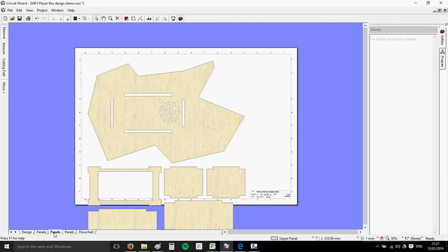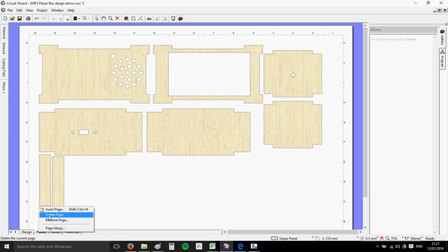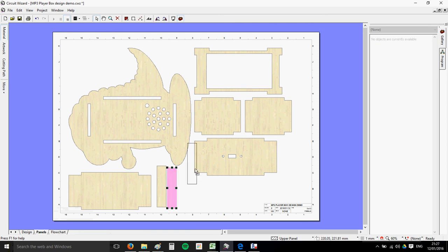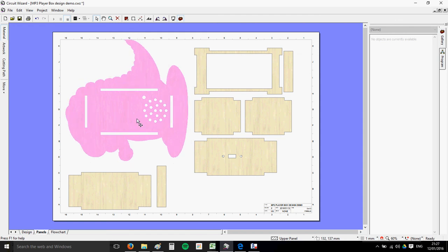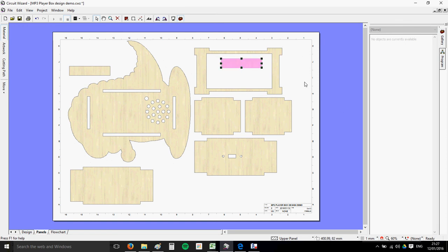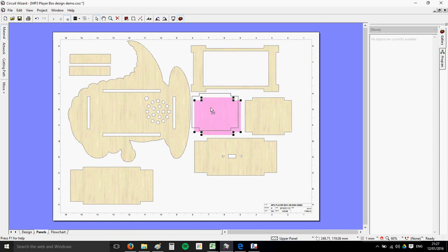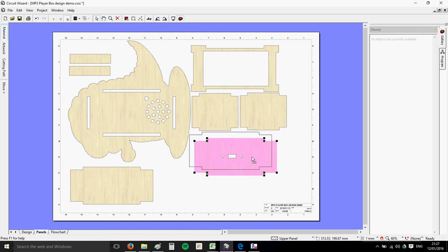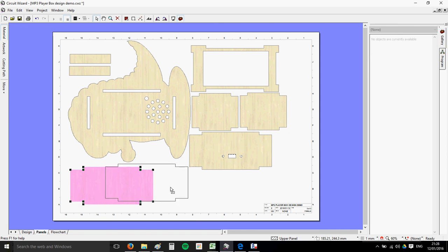I then want you to tessellate the bejesus out of this. Tessellate, if you're unfamiliar with that, let's do our numeracy link for today. We love a bit of that. Tessellate means to make shapes fit together in the most efficient way possible. We're doing that to save laser cutting material. So rotate bits. You might be tempted to put that bit inside of here, but don't do that, because remember, you're going to need the bit that comes out of there to be your battery door. Alright, so really just get these as close as sensibly possible to minimize material, and make it as rectangular as possible so the technician has an easier time laying it out on the machine.